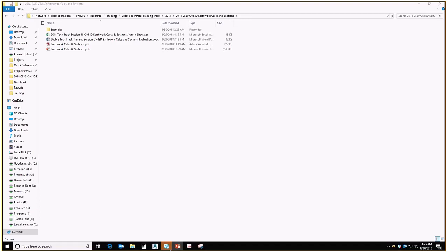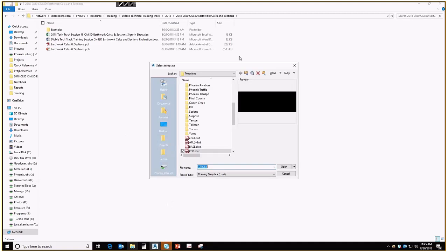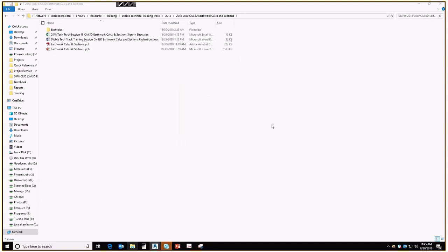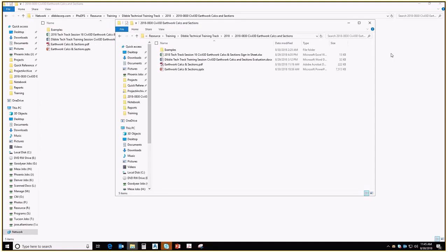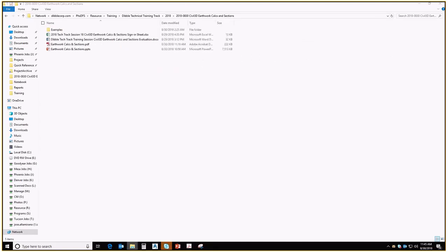So once we've applied the ground compaction and the shrink swell and run Civil 3D, those are what we call adjusted earthwork numbers. And in a lot of our projects in the airport group, we're forced to use unit price, and contractors, we have to estimate earthwork. The FAA requires that we use average end area. And so we have a bid item in our plans for earthwork volume, cut and fill, and we often get into arguments with contractors about those items because they come up with slightly different numbers than we do.